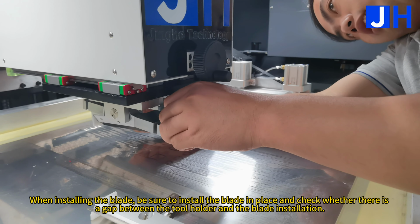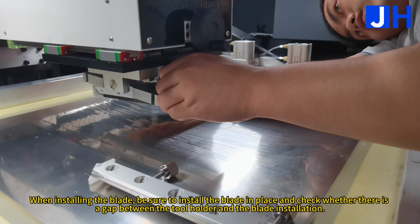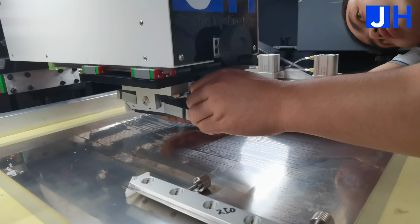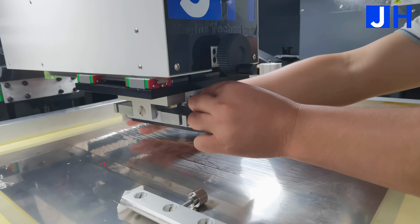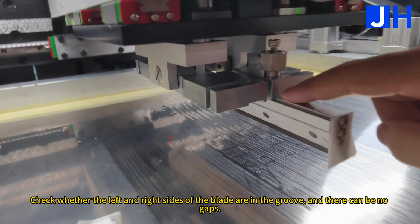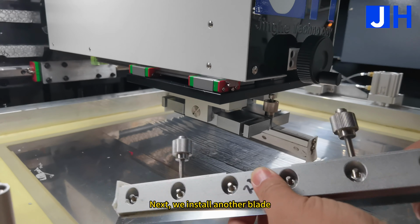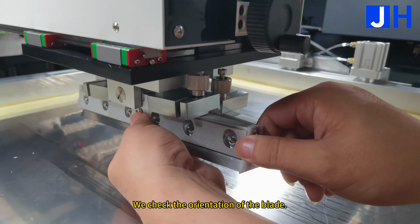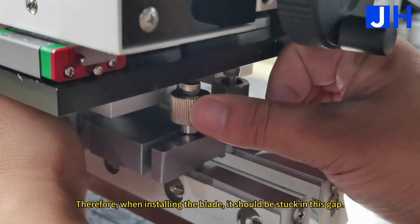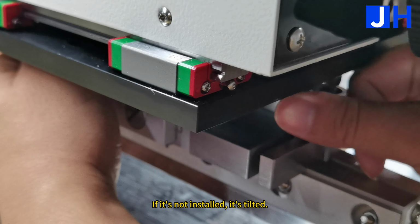When installing the blade, be sure to install the blade in place and check whether there is a gap between the tool holder and the blade installation. Check whether the left and right sides of the blade are in the groove, and there can be no gaps. Next, we install another blade. Examine this gap. We checked the orientation of the blade. Therefore, when installing the blade, it should be stuck in this gap. If it's not installed properly, it's tilted.